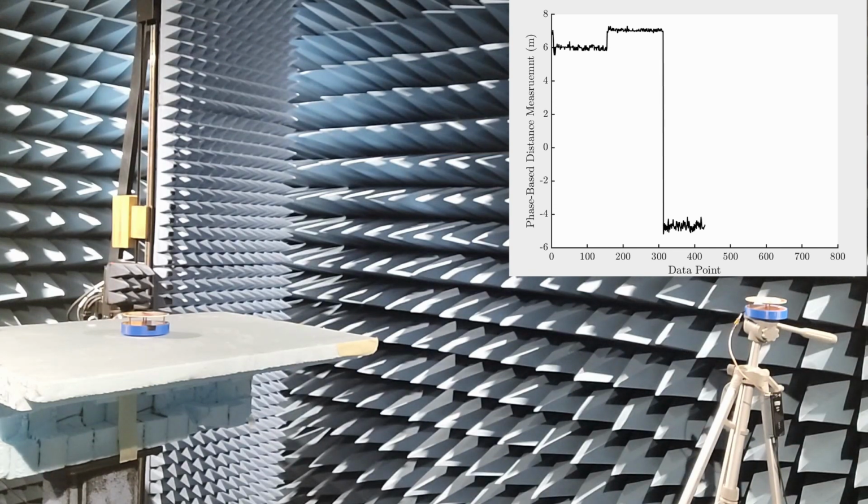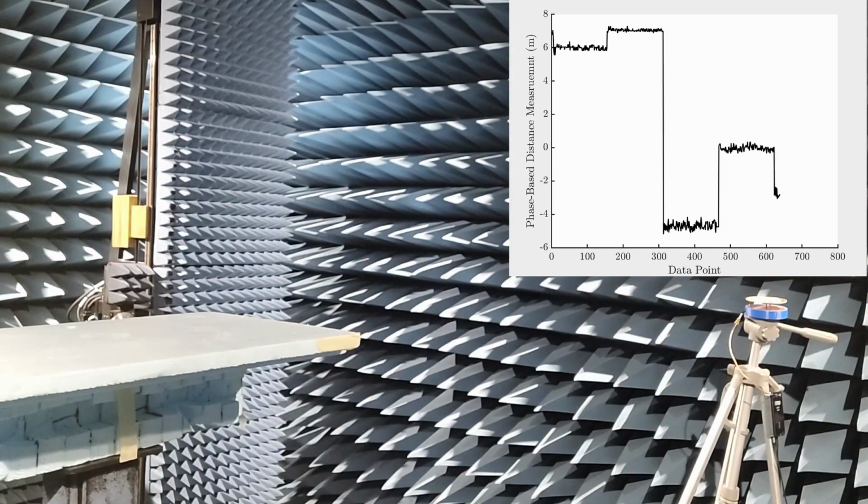The system is not able to measure the absolute distance, nor do the phase measurements reflect the monotonically increasing distance of the tag. It was found out that the selected reader imposed some limitations, where the in-phase I and quadrature Q received signal strength indicator or RSSI values are always positive. Thus, the calculated phase is always between 0 and 90 degrees. The reader provides a phase bit that indicates the sign of the Q over I ratio, though this is not sufficient to determine the phase quadrant.